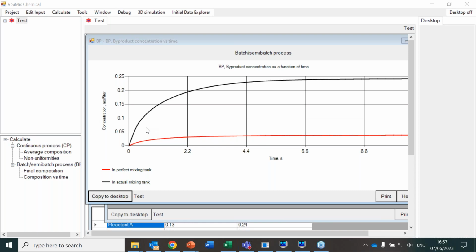So we write the differential equation for mass transfer, and instead of the velocity, we feed in the mixing consideration. This gives us the mixing eddies, the velocity of the eddy, the macro mixing time, and the capability to generate results for how long the material stays connected according to turbulence theories. We hope to have this in a paper or some explanation inside the software once we release it in 2-3 months.